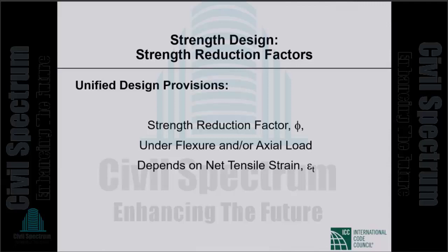Okay, so under this unified design introduced in 1995, the phi factor became a function of the so-called net tensile strain, a very important term now, epsilon sub t.